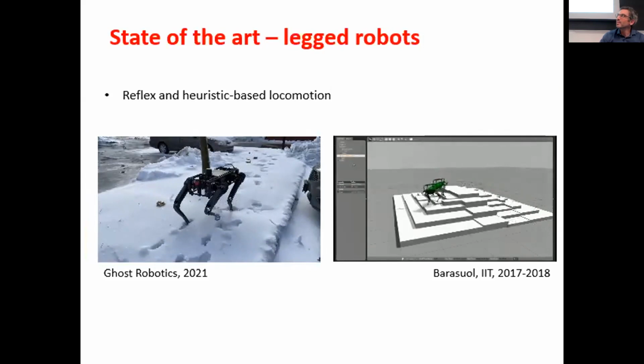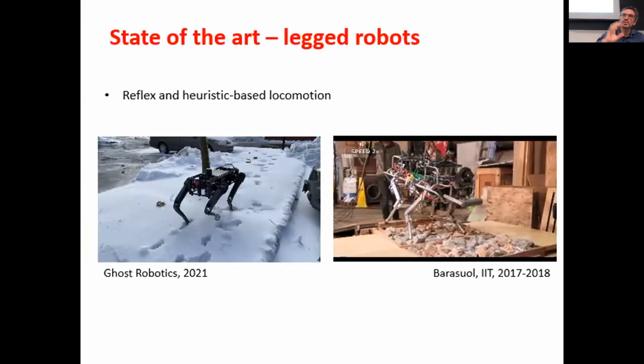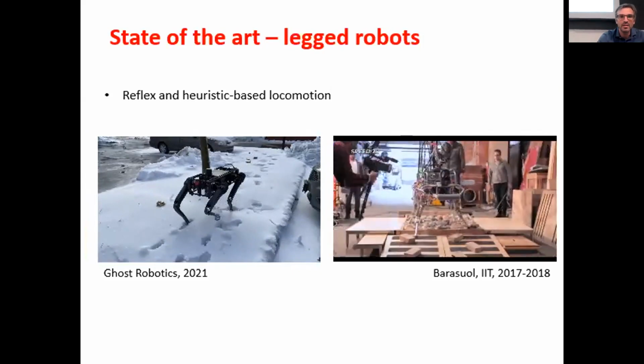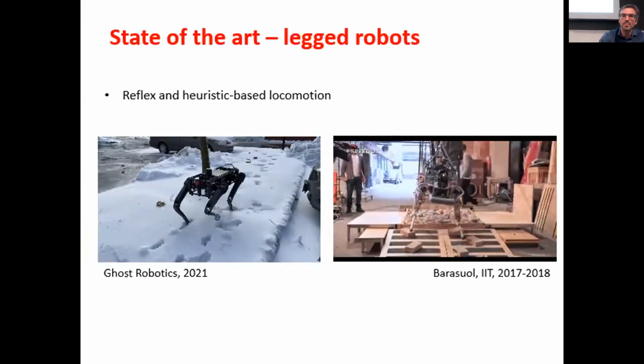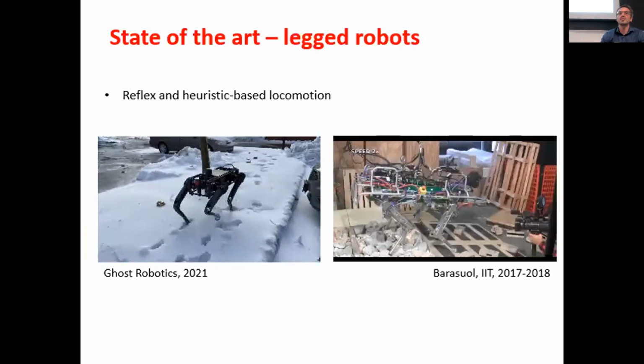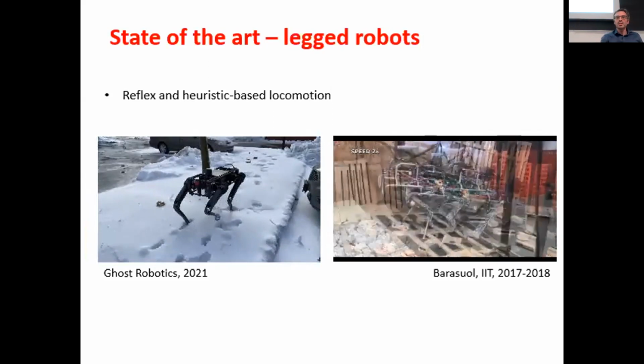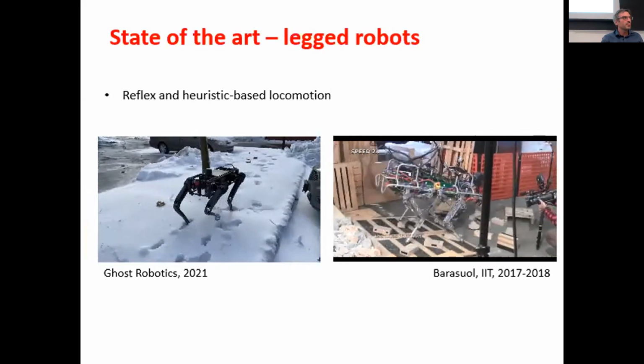So we implement our code in simulation. We don't test on the robot first. We first try in simulation, and then we test on the robot. In the pyramid that you saw before, it was our simulator called Gazebo, where we were trying our trotting. Once everything works in simulation, we try on the real machine. This way, we are sure that we don't make big errors, because we can break the robot if we do the test directly on the robot. So the simulation is very important.